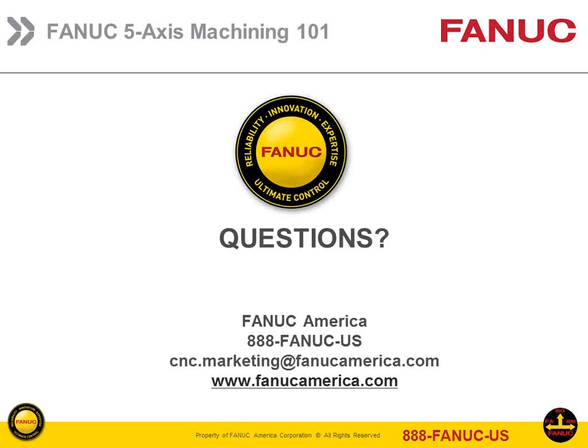Because, as Rick has really beat into my head, and then I tried to reiterate it in our presentation today, one of the first things you need to do in the program, you've got to identify the part location. You've got to tell it where it is. So that's why it's critical to use the Workpiece Setting Error Compensation along with the tilted working plane. You've got to tell the machine where the part is. It's important that you do that.